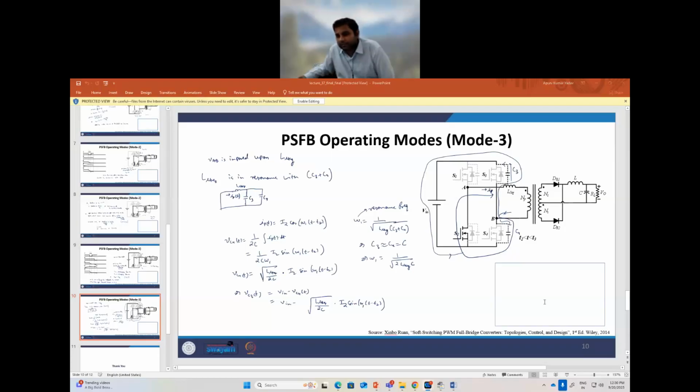See, the answer is, if you are not using the diode and are realizing the totem pole using active switches, then obviously there is a possibility that you can make it operate in a bidirectional mode also. But you have to use the bidirectional switch. If you cannot use it, then you can operate it in a PWM mode.